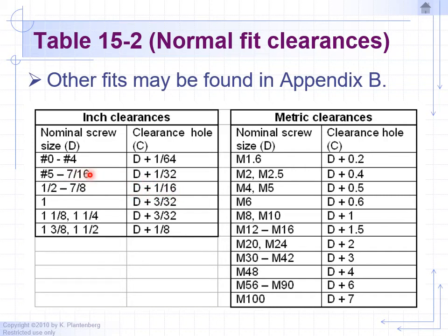And if you're dealing with smaller diameter, we're going to go with the 1/32. So 1/32 is about the thickness of a credit card. Okay, so take whatever diameter you're using from this range, and your clearance hole will be that diameter of the bolt plus 1/32, which is about plus or minus 30 thousandths, 0.03125 to be exact, and that's about the thickness of a credit card. And for metric, we use this table.